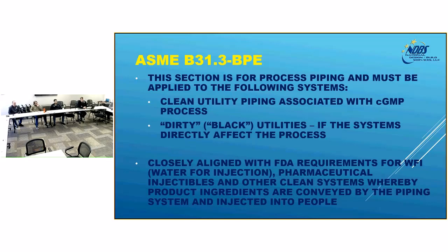So what are these requirements? It's the categories of the fluids in some cases. It's the test pressures, operating temperatures and pressures, PSV set points, system design pressures and MAWPs, the NDE requirements. It's everything I've discussed that becomes part of your ETOP. All that needs to be from the owner. So if there's an engineer involved, 99% of that's going to be in the engineer spec. If there's not an engineer involved, and we're doing this kind of work, we need to develop this information hand in glove with the owner.